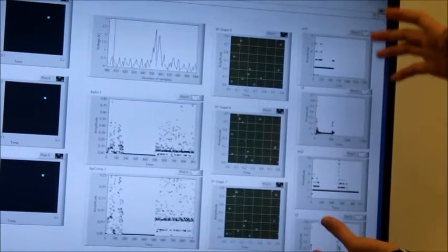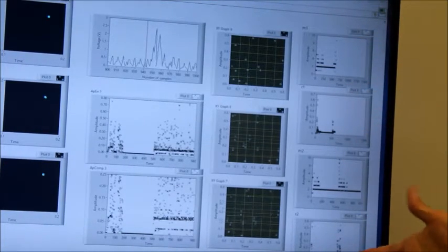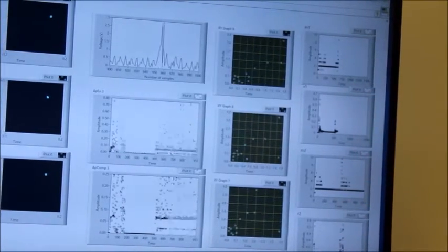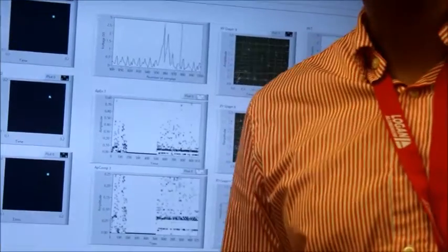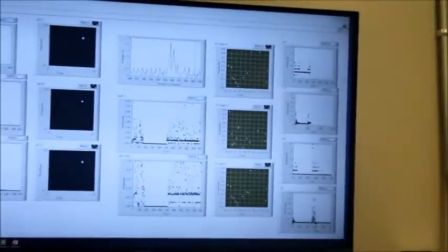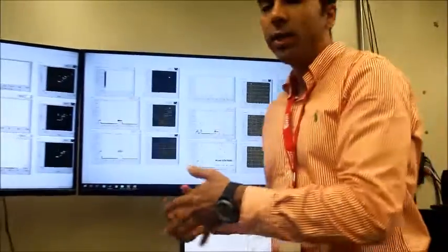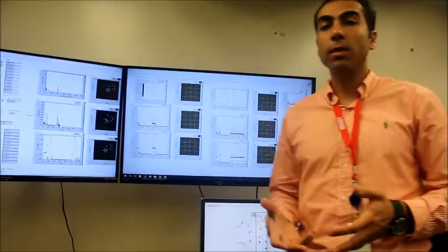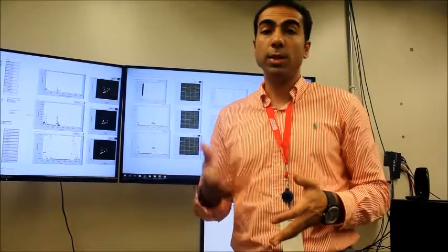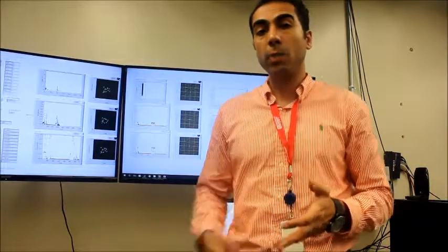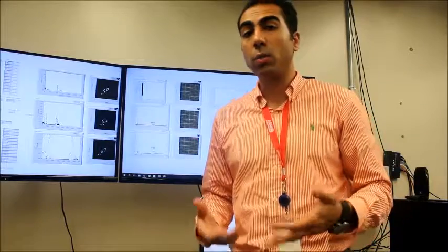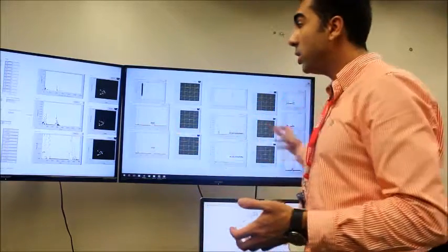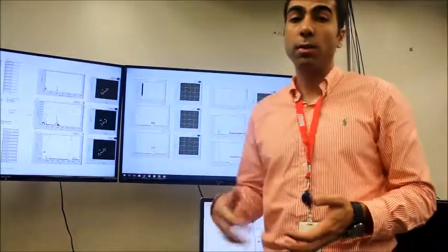Also, if you consider these parameters associated with the phase space, the number of dimensions and filtering level, you can see the change at the time islanding or fault or load switching occurs. So these results validate our proposed technique, because they have been able to detect dynamical changes in the system with 0 time lag between the event and response. In other words, the calculations of the complexity are all in real time.